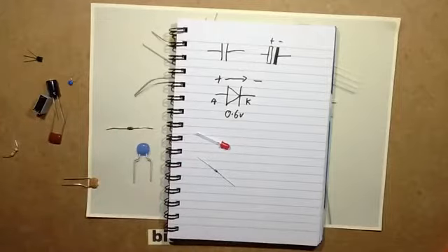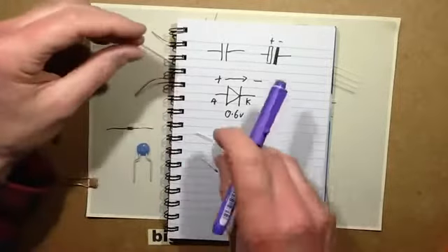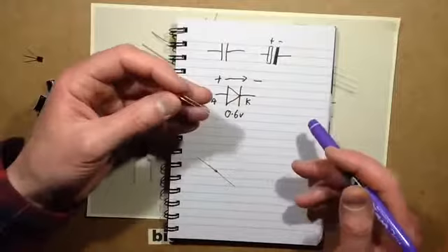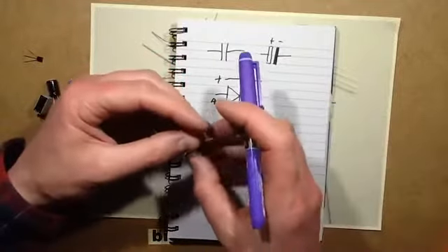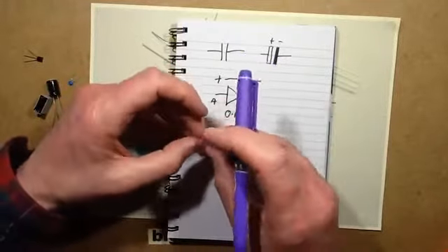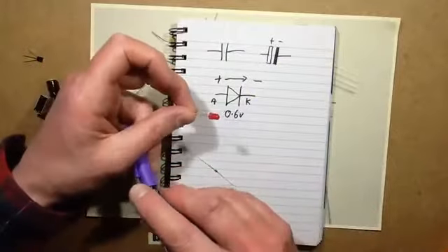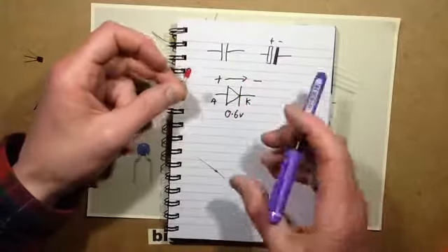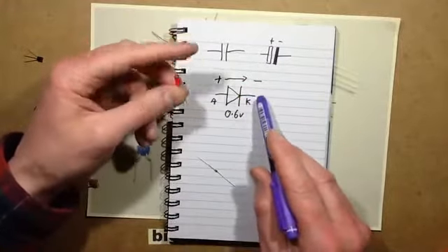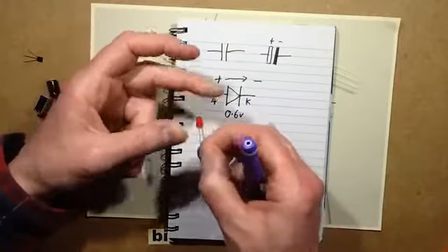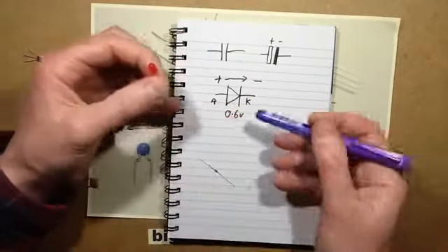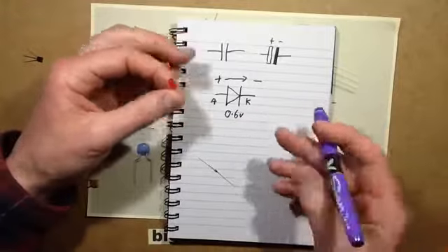It's very, very dim, but they were purely for printed circuit board indicators. These days, of course, LEDs are used for illumination. They've evolved greatly. But one of the things you have to note with an LED is that because they're optimized for emitting light, they don't have a high reverse blocking voltage. It's usually just about 5 volts.